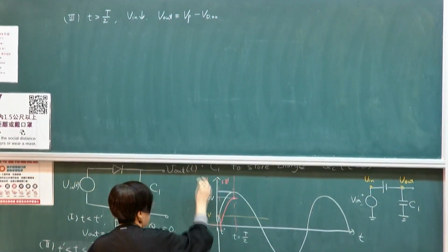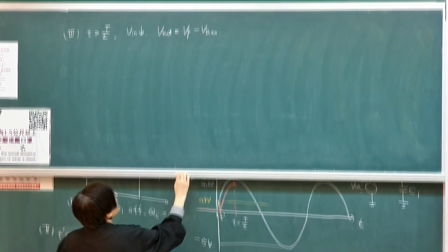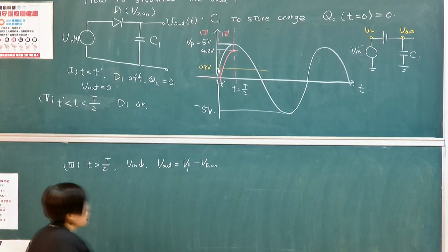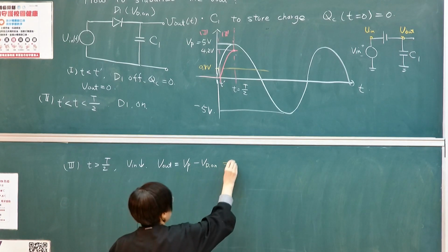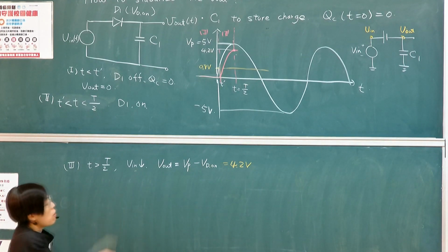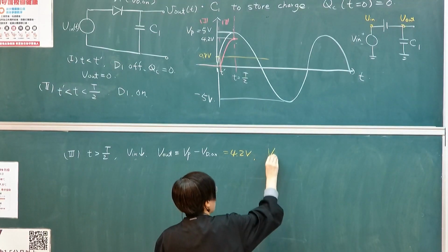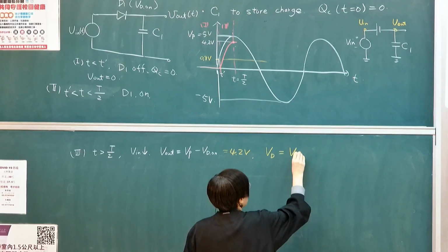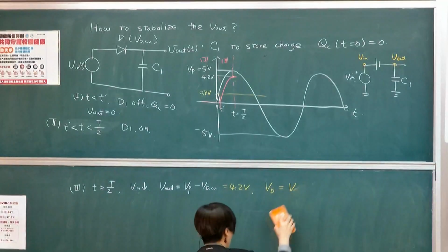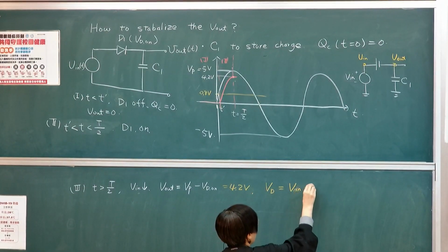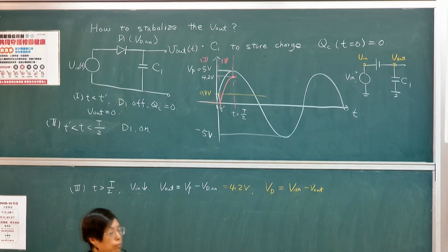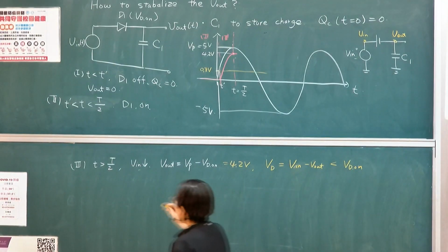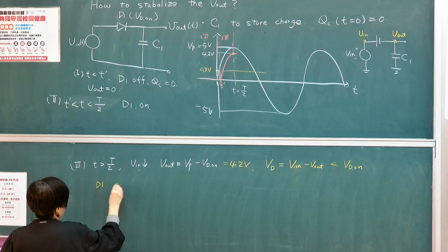I just want to give a general number. So this is the peak level. So your VL is also at its peak level of 4.2 volt, if I'm using the number. So this would then fix at 4.2. But your V-in starts dropping, so this would then make the voltage on the diode become, I should say V-in. Remember, the voltage across the diode is V-in minus VL, right? So this would then give me a number less than VD-on. That is to say the diode is then off.